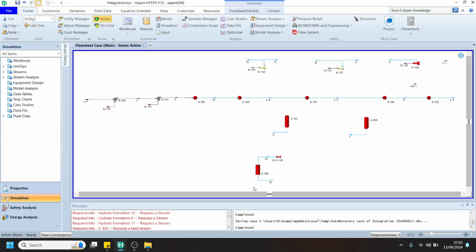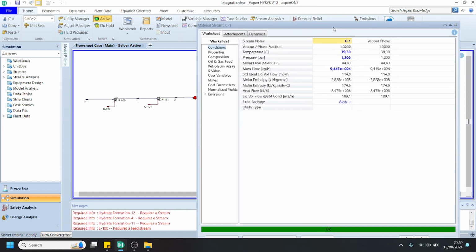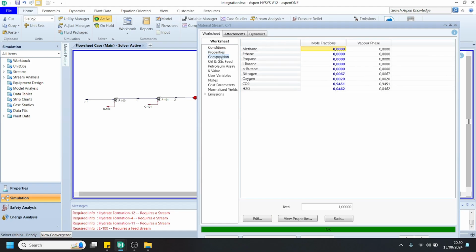We can observe the CO2 stream here that we will pressurize and convert into liquid phase. You can use this operating condition, and you can specify a random mass flow here as the initial value of our CO2 stream, and we can see the composition. You can use the following data. Actually, I took this data from the reference.